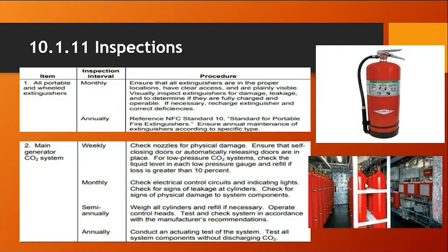So, semi-annually, weigh all cylinders and refill as necessary. Operate control heads, test and check the system in accordance.